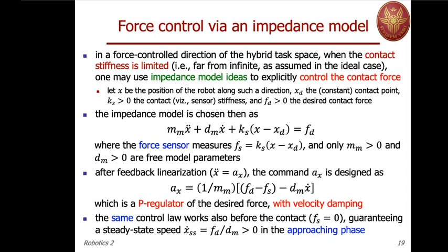In that case, the measured force is 0, and by the choice of positive gains, M and Dm in particular, in the impedance model, you can recognize that you start from rest, you get a force in that direction Fd, and this will let the system start to move, but because of the damping Dm, you will reach a steady state speed.